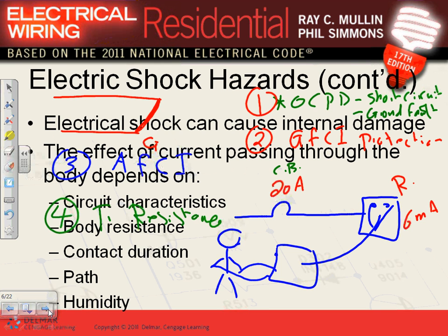The fifth protection on this circuit, and the last one, believe it or not, my friend, is weatherproof. Weatherproof receptacles, guys, in only wet location. You sit the receptacle outside, heat and cold, and all the sun rays are beating on these receptacles. If it's not weatherproof, it's going to fall apart.